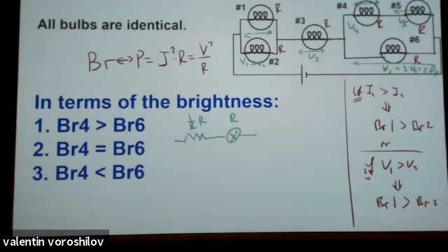Now this. So this is trickier. So first I need to simplify at the top. There's going to be 2R and just an R at the bottom. These are in parallel, so I want to replace these, and that should be equal to 1 over (1 over R plus 1 over 2R).